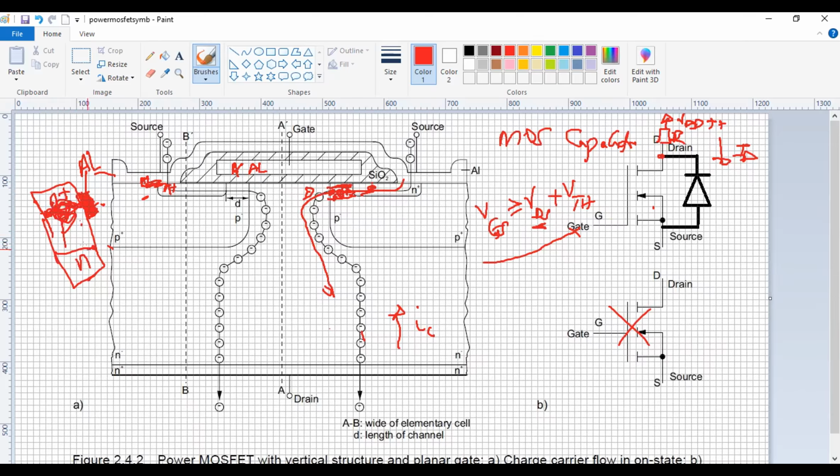But of course, you can see that the PN remains. You have this PN junction. Although I've gotten rid of the BJT, I still have a diode, a diode within the body of the device. So that's where this diode comes from, the so-called body diode. This diode that I've drawn is internal. It's part of the MOSFET, which is why I added that this is an internal diode. It is part of the device internally.